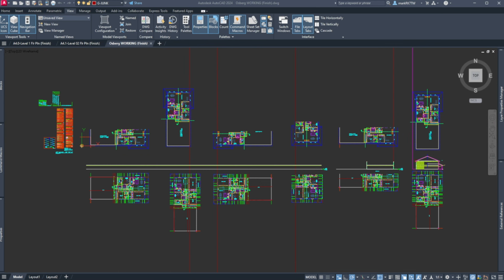Another part to go in your notes is that no stair, well, let's just read it the way they put it. The greatest riser height within any flight of stairs shall not exceed the smallest by more than 3/8 of an inch. So that is within a flight. If there's a landing, you can change sizes. But you've got to keep it within 3/8 of an inch of each other, the total rise, which is the height that you're stepping up.